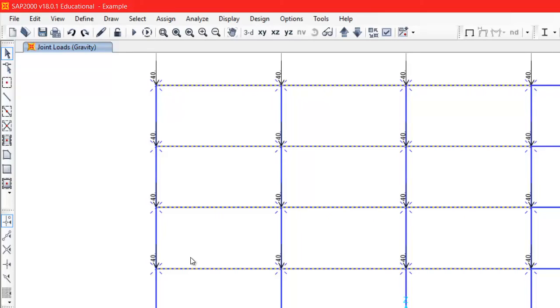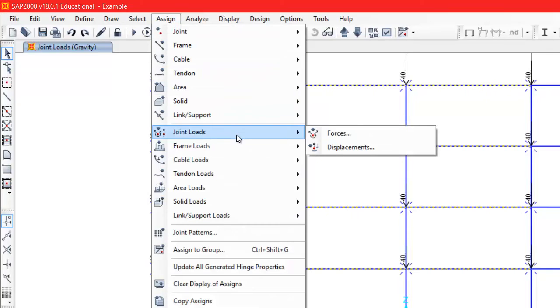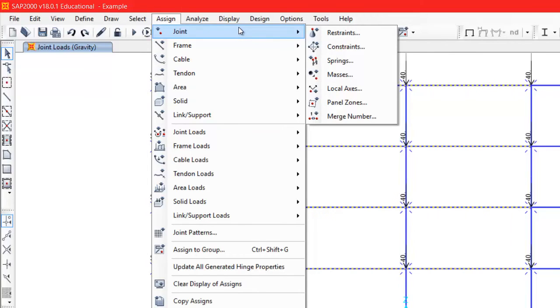So you have this load, you divide it by G, same units, and then you got your mass, then you divide it by 4 nodes. I don't need the leading column here, okay? So we divide it by 4 nodes equally, it doesn't matter, because the mass is only giving inertia, nothing else. Inertia forces. So I select again the nodes. I say assign, joint masses, the first one, all right?